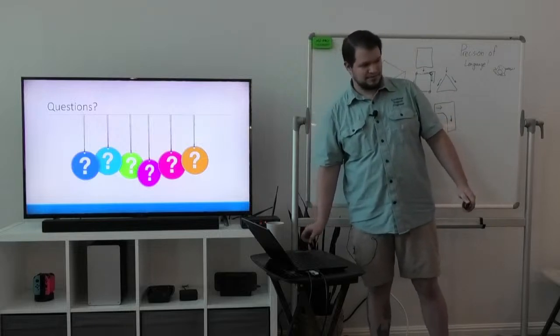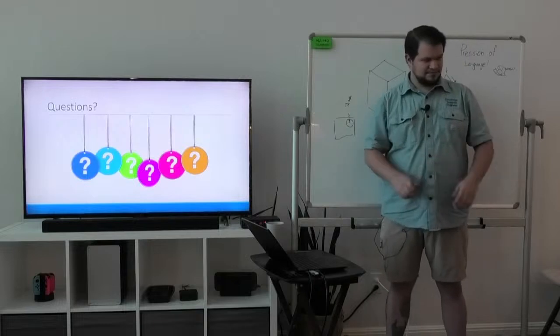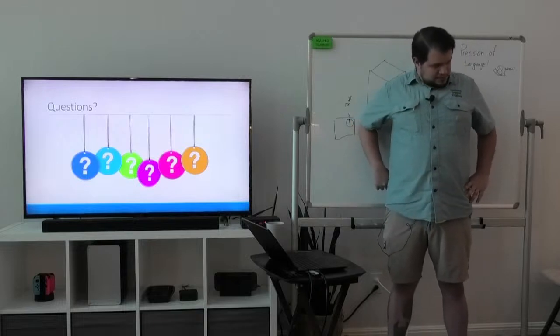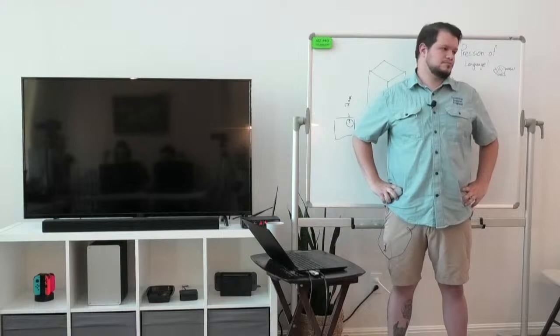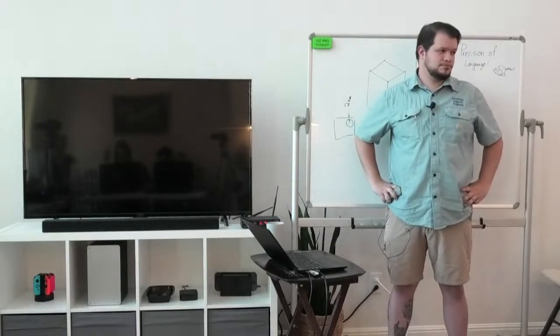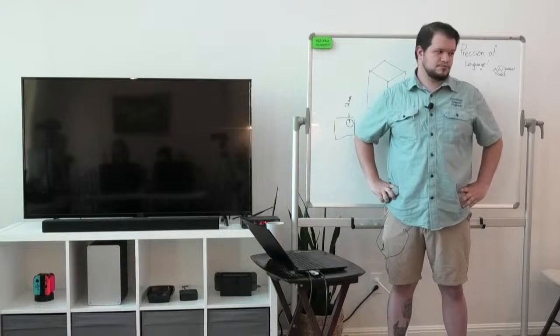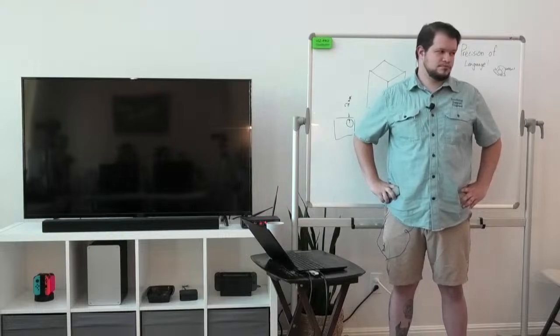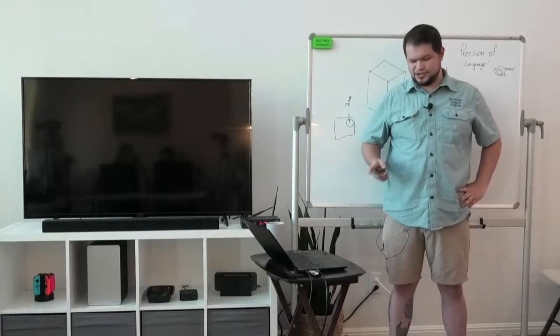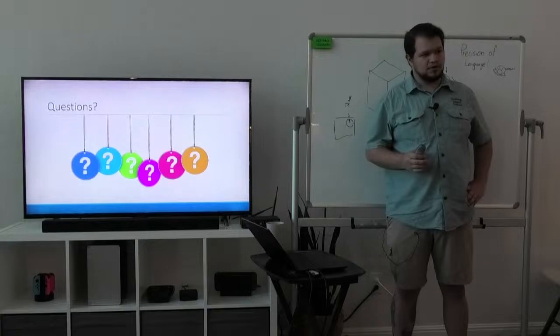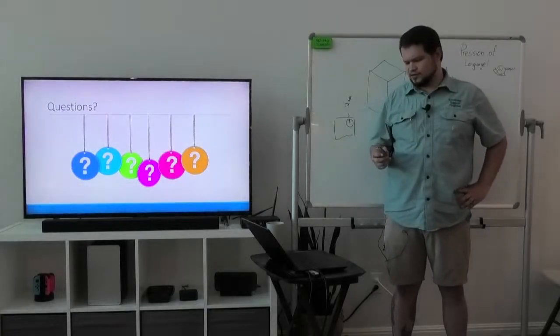Speaking of 3D printing design principles, one thing that I've encountered while designing is for one part that I originally made, one of the clips that I had, the clips faced horizontally outwards. And when I printed it with support material, I couldn't get the support material out, so I changed it for the clips to face upwards so that I could print it better without support material there. Correct. So orientation, again, matters when you're printing.